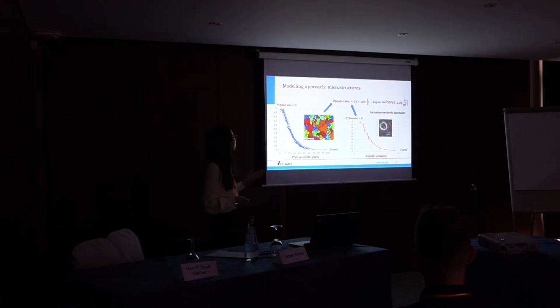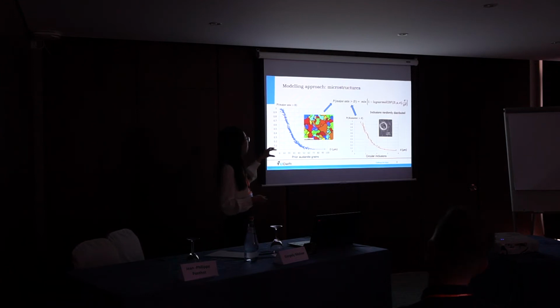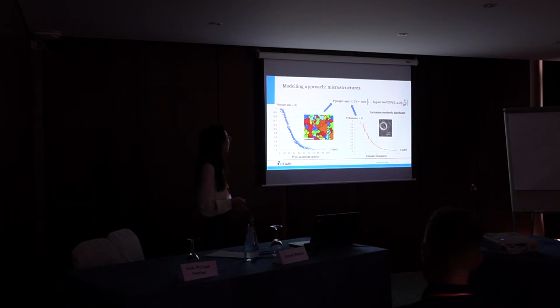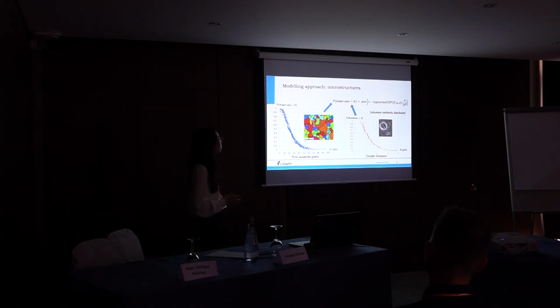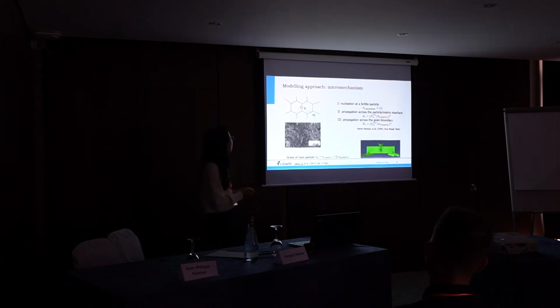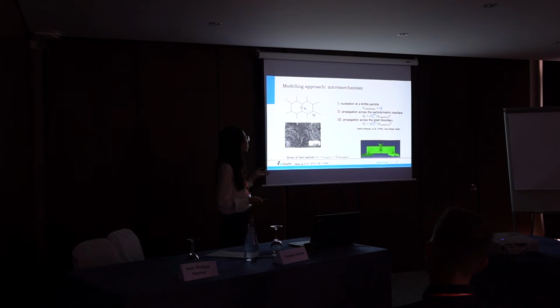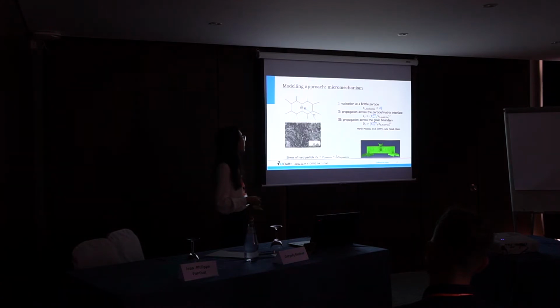For the inclusions, we did similar work. We measured the inclusions from the EBSD scan, and for each inclusion, we measured the diameter from the geometry, and we fit with this same equation. Then we use this equation in our model to estimate the cleavage probability based on these three equations.